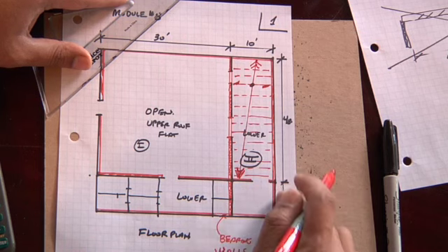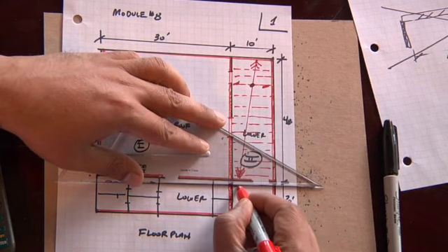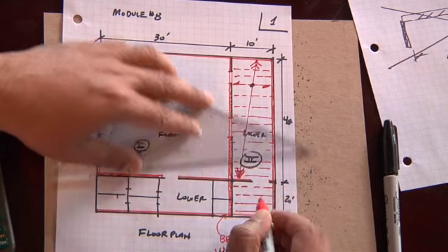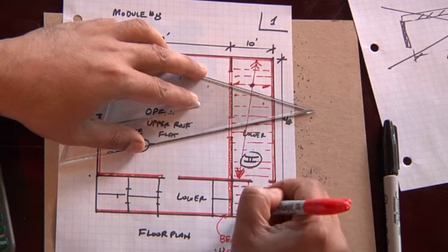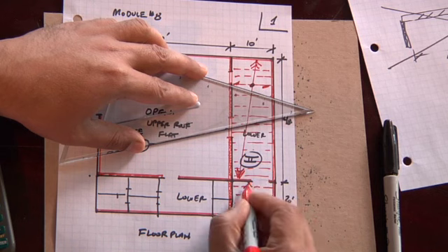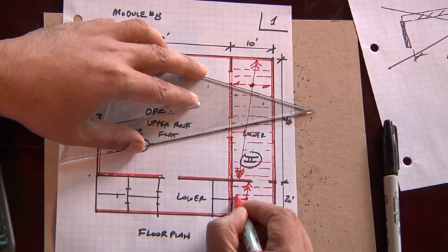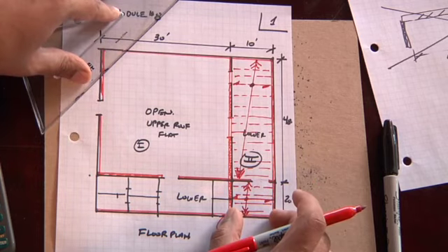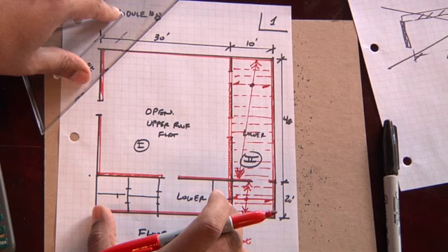We can actually, this is 20 feet, so we can actually continue that spacing all the way down here, same exact designation, except that we stopped over here for the bearing wall, and we're going to run the rafters along the short span, which is the 10-foot span. In this direction, exactly the same reasoning.